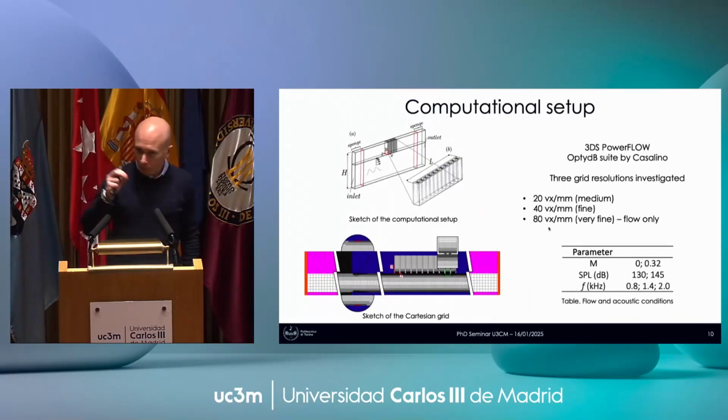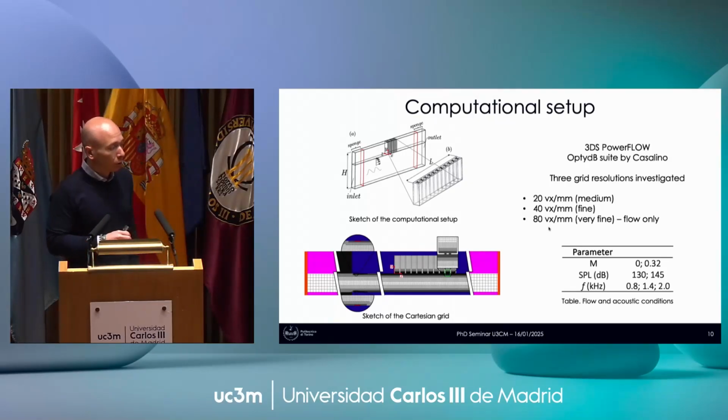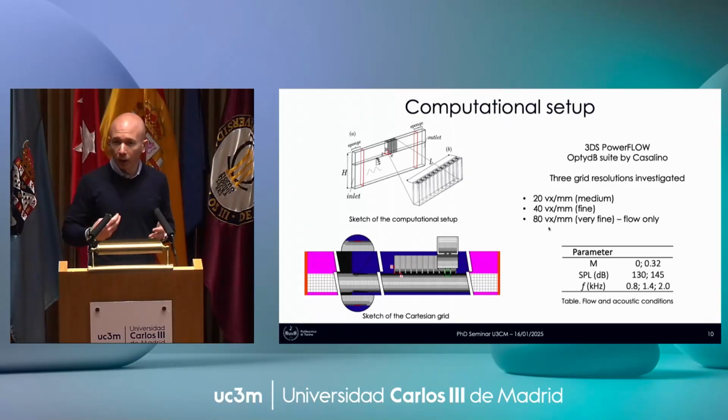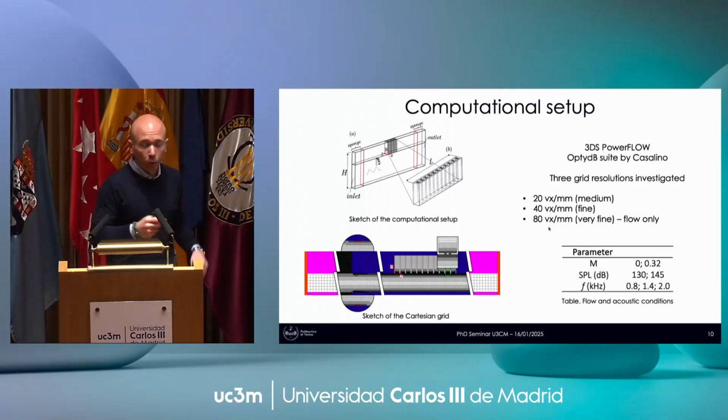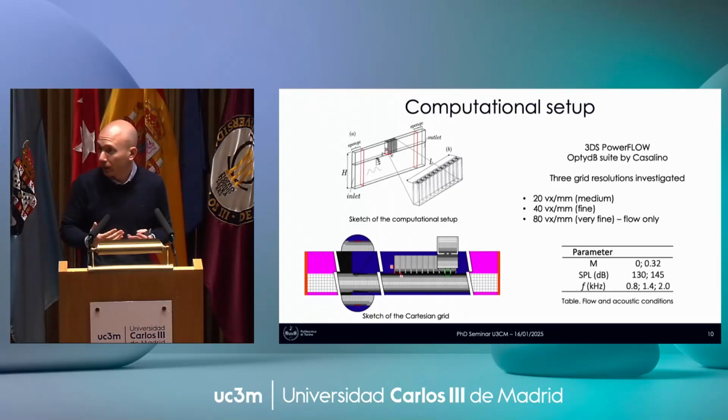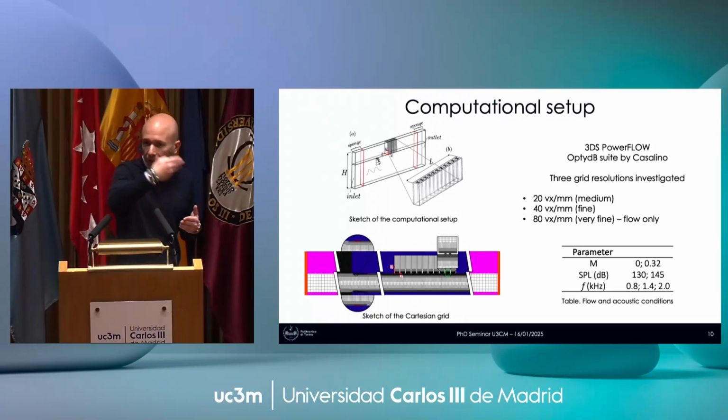Then we built up the numerical setup, and the numerical setup was built such to inject at least an acoustic wave with 15 wavelengths. So the acoustic wave is not added as a boundary condition at the inlet, and the reason is that in order to avoid reflections at the boundary of my domains, I must use on both boundaries of my domains some numerical sponges. Else, I arrive at the end of my domain, I see a discontinuity in pressure, it is a compressible solver, the acoustic source comes back and this corrupts my measurements. It's not as in the experiment. So we decided to add the acoustic wave in space and then to let it propagate.